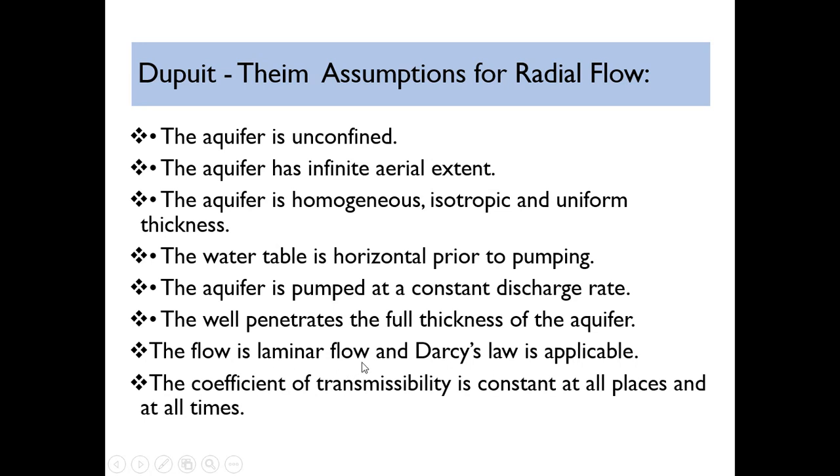The flow is laminar and Darcy's law is applicable. The important assumption is that the flow is treated as laminar flow into the well, and Darcy's law is applicable: Q equals K into I into A. The coefficient of transmissibility is constant at all places and at all times.